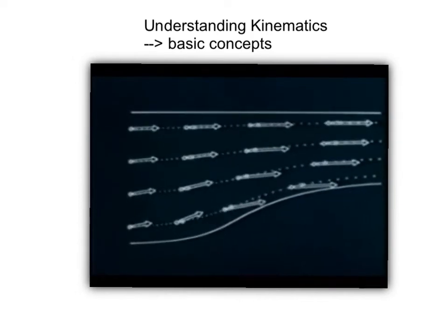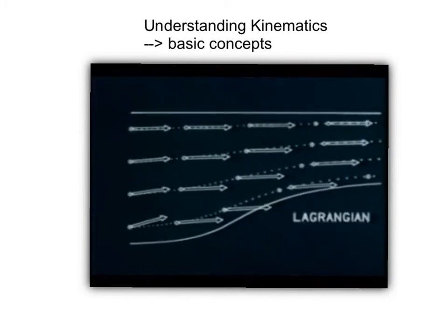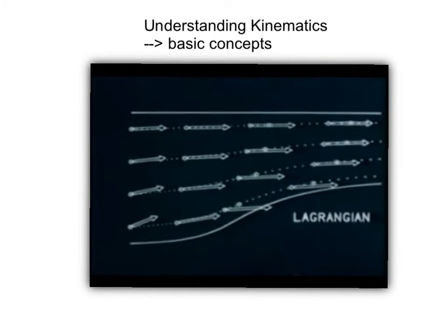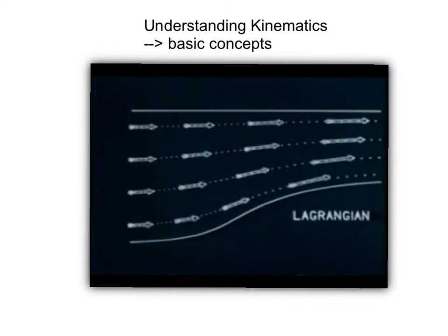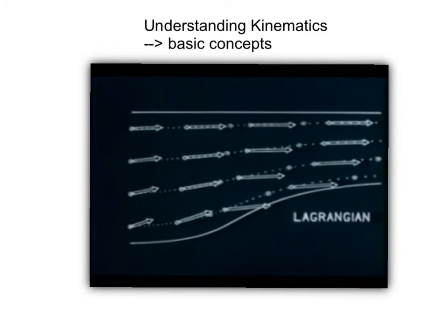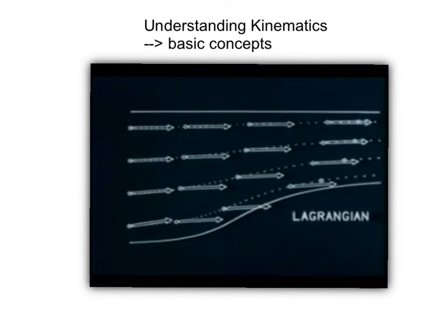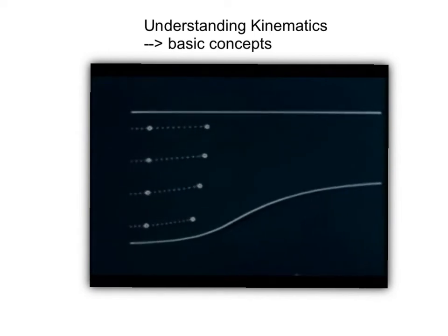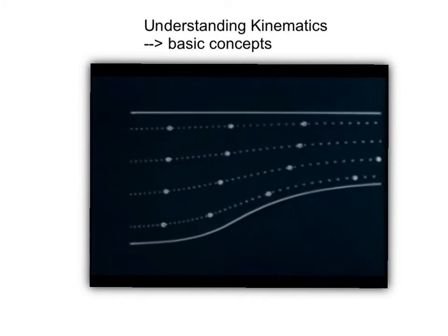This description, in terms of material points, is called a Lagrangian description of the flow. Such coordinates are called Lagrangian or sometimes material coordinates. From the Lagrangian velocity field, we can easily calculate the Lagrangian displacement and acceleration field. We can imagine attaching an instrument, like a pressure gauge, to a moving point to make what we might call a Lagrangian measurement.